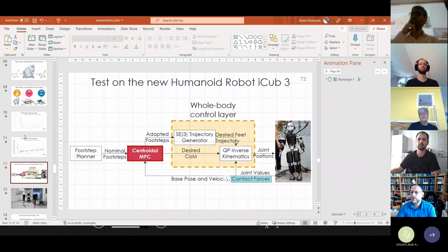More than the controller, the estimator, because the estimator that they have right now computes the joint torque estimation using only the information coming from the nearest joint, while what I implemented, which is described in more detail in the thesis, is a complete recursive Newton-Euler algorithm. So we also consider the forces acting on the system and the measured joint torques. They are interested in this part.